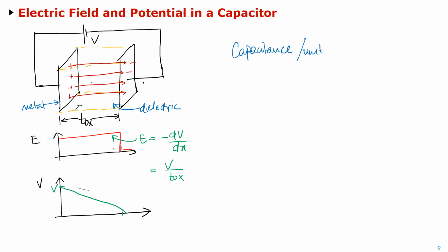And the capacitance is just given by the relative permittivity times the absolute permittivity, the product of that divided by the distance, right? So that's what's called your linear cap, in the sense that your Tox is not varying with your applied voltage like it was in the case of the diode. This is just a simple cap, but I wanted to show you that inside the cap the electric field is constant because there are no charges. Since the electric field is the negative derivative of the potential, the potential varies linearly from this plate to this plate.